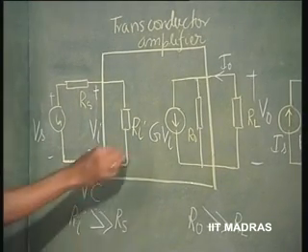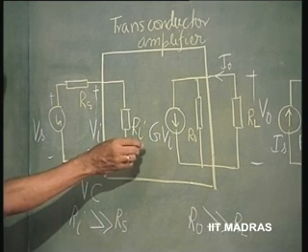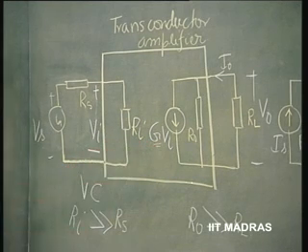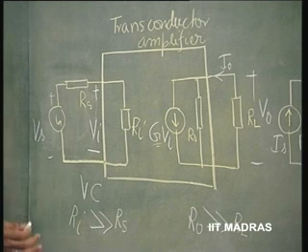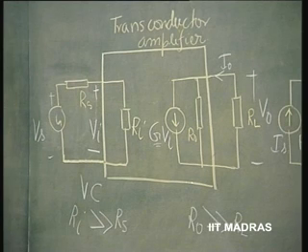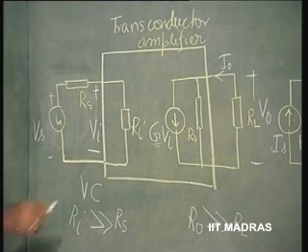And the most important parameter of interest at that point of time is the transconductance. However, we can still evaluate the voltage gain and current gain for this circuit, and power gain again, in the same manner as we did earlier, even though the important parameter associated with this has to be recognized as transconductance.